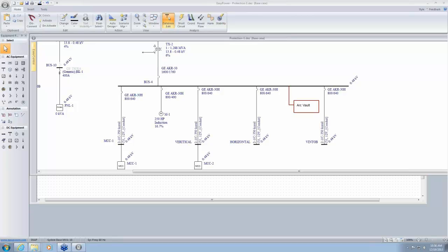Next question, can you discuss switchboard versus switchgear and how to handle labeling for each? Typically when we talk about switchgears, we assume that all the different components are in separate cubicles or compartments. So the main bus will have its own compartment that is enclosed by metal, and each of the circuit breakers will be in separate compartments.